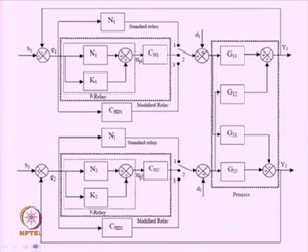Now, this will be the block diagram that will be used finally for identification of 2 input 2 output systems. So, please observe carefully, this is the 2 input 2 output process or system dynamics given by G11, G12, G21 and G22. Okay. Now, what are these? These are the load disturbances, static load disturbances. So, D1 and D2 stands for the load disturbances present during the relay experiment.